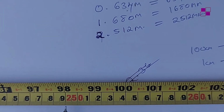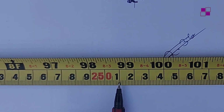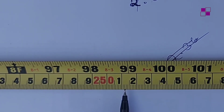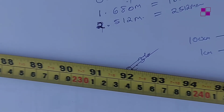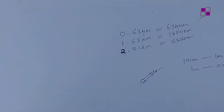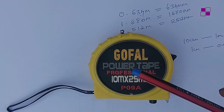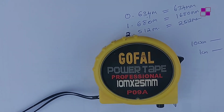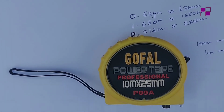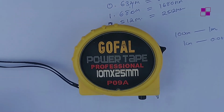All right, so the next one is 2.512 meters, right? So you just go 2, and this is 5. Then the next one is 1, and then the next one is just 2. You count 2 after the 1, 2 points. So that's how to take your measurement. I believe this is simple. The problem that people have, when I first came to site, I had this issue of not understanding that measuring tapes might have been written in meters, but the scaling is in centimeters. So I had to do some conversion by myself to get my measurement either in meters or in millimeters.